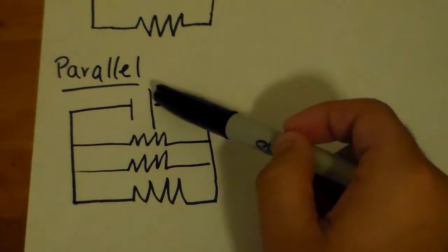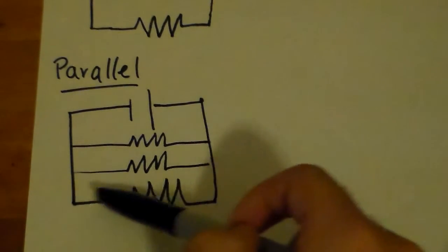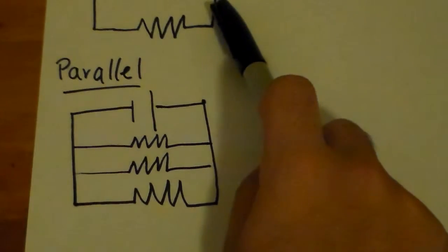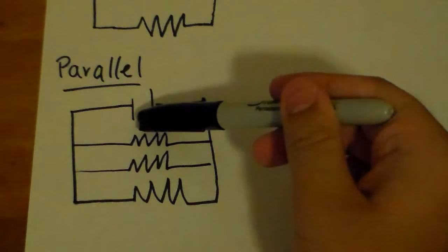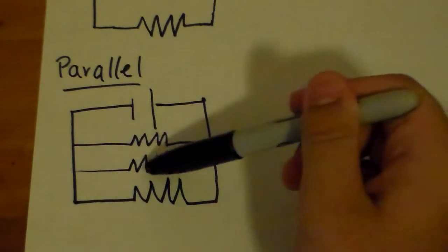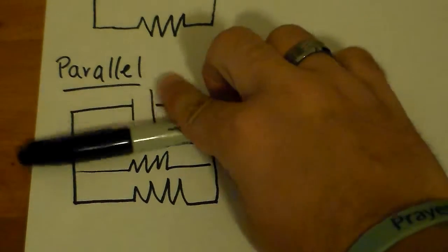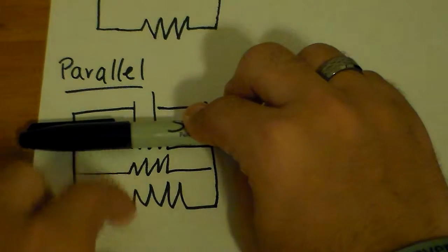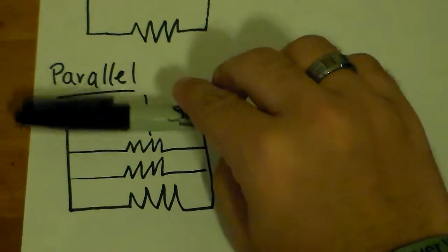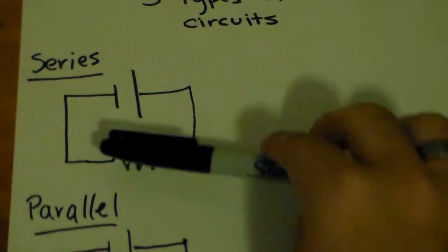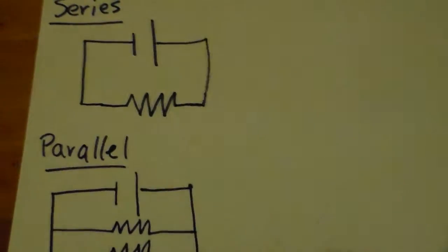If you were to turn on this power source, it would go to the lights, the microwave, and the stove, like a series circuit would, but if the lights happen to go out in the kitchen, the microwave would still be going and the stove would also be going. So, if one thing was taken out, the other things would still be working. But in a series, if one thing happened to be out, everything would be out. See the difference between parallel and series?